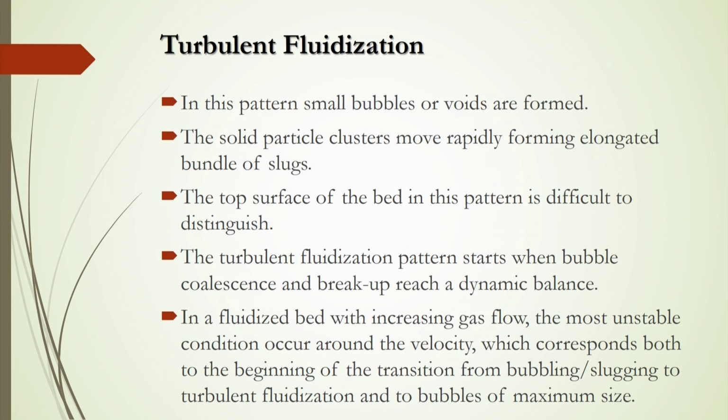The turbulent fluidization pattern will start when bubble coalescence and breakup reach a dynamic balance. Of course, there will be a simultaneous happening of coalescence and breakup of the bubbles inside the bed during this turbulent fluidization. So, for smooth bubbling condition, there is smooth coalescence, but breakup will be less, whereas in the turbulent condition, because there